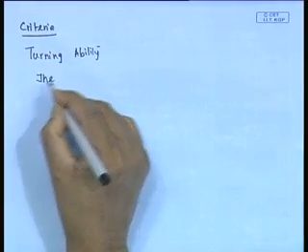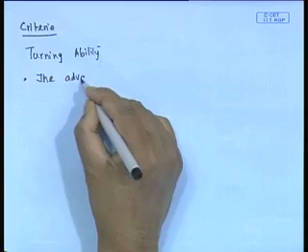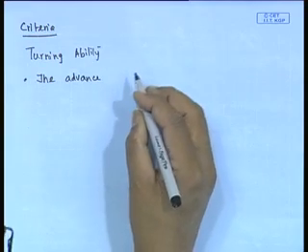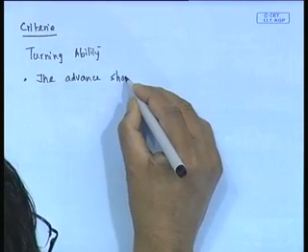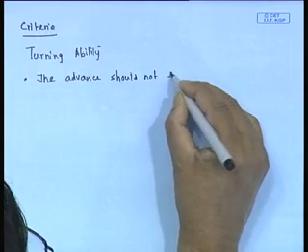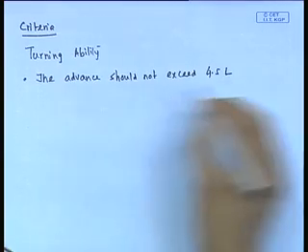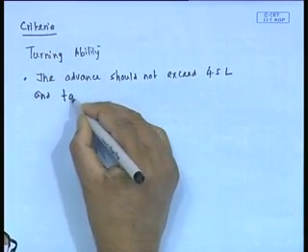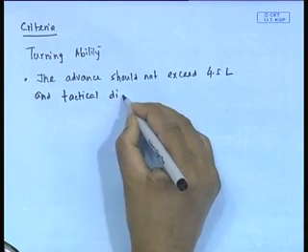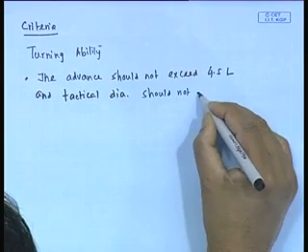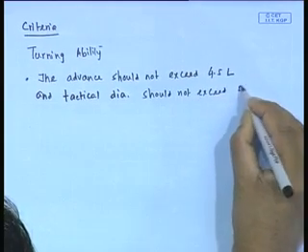Here, the advance means the distance it moves forward when it has changed 90-degree heading, which is also specified earlier. Advance should not exceed 4.5L.